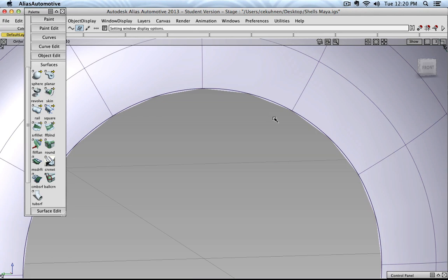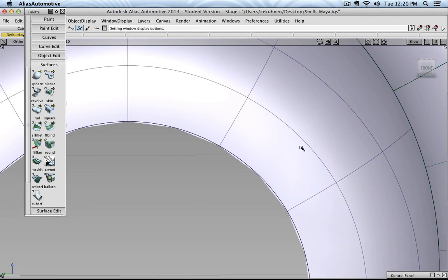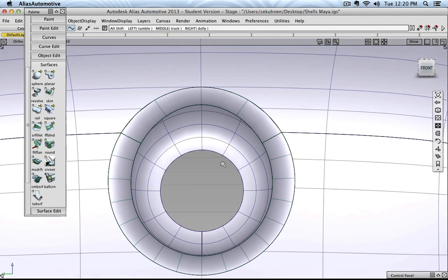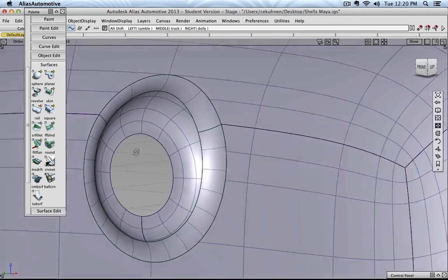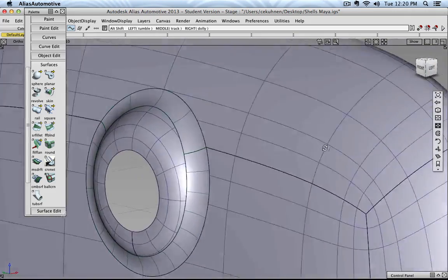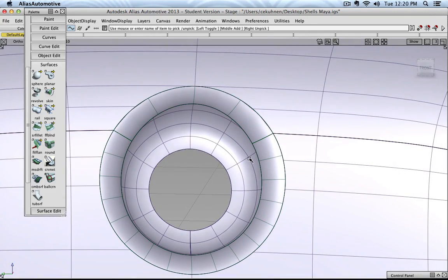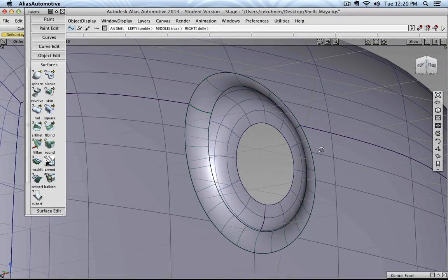And that actually is true, but NURBS itself is just math and just a lot of lines. To shade it, Alias has to create a polygon mesh based on that input. It works actually similar to the way the subdivision surface modifier in Blender works, where you have a low polygon cage and then a much more refined shaded mesh inside.